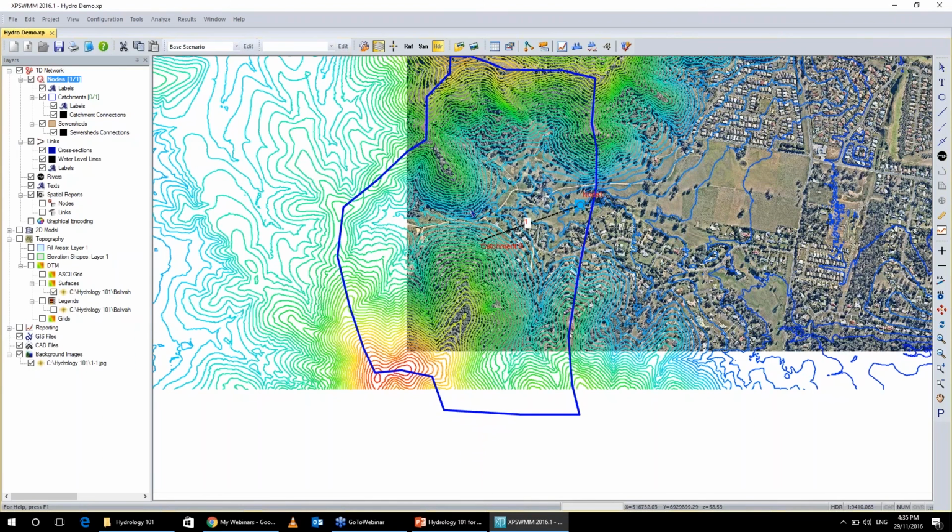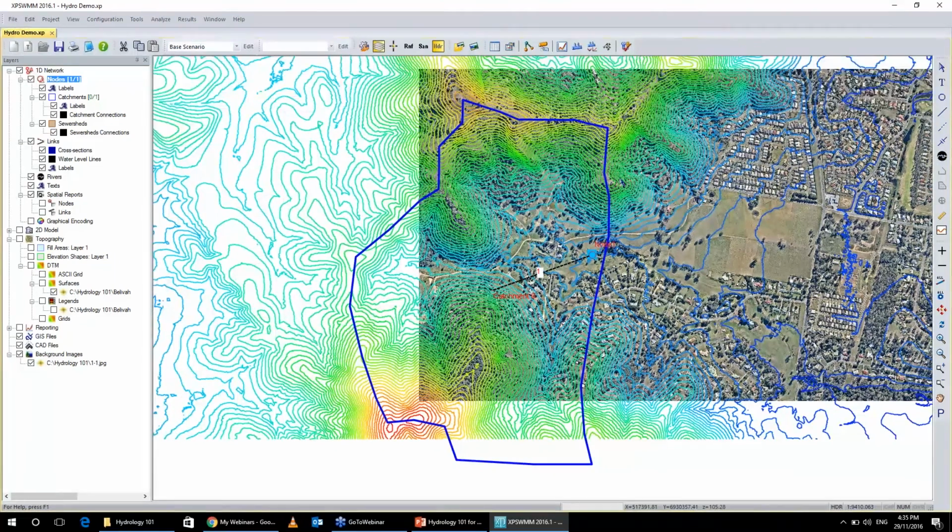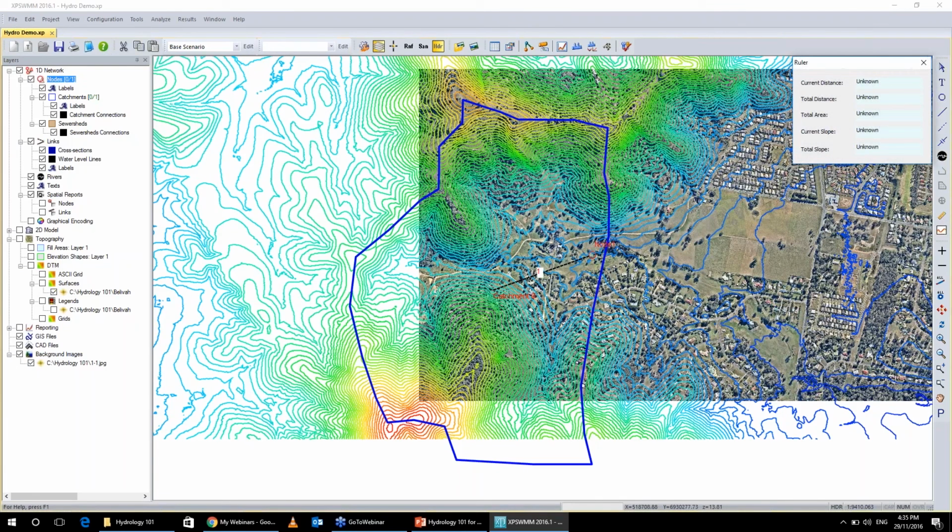The next tricky thing that I have to work out in this catchment really is probably the slope. And I've picked a pretty hard place to do that because I have lots of varying slope up the ridges through this creek zone in the low contours. But I do have a ruler tool on the right hand side, and if people aren't familiar with this, the ruler does give me some options to try and calculate slopes, and it is dynamic, so it doesn't matter where I go, I can try and get my slopes.